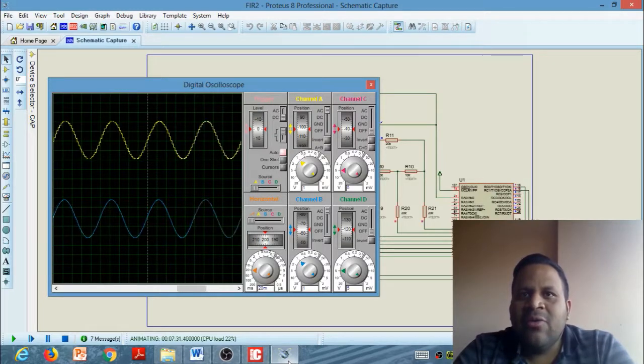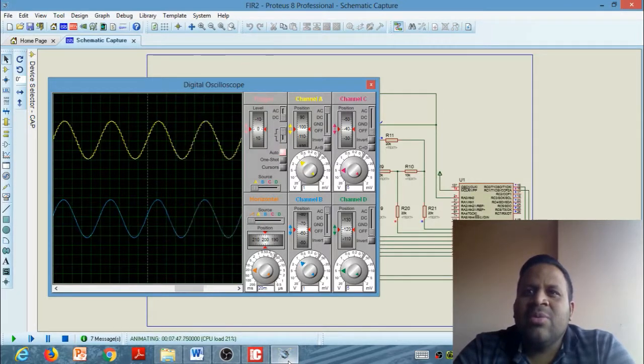ISIS has a default frequency of 1 Hz and amplitude of 1 volt. The acquisition of the signal is done in the microcontroller by means of the ADC module. The voltage levels that the analog inputs admit cannot go outside the supply limits of the microcontroller. In other words, the level of the analog inputs cannot be higher than 5 volts, nor a negative voltage.